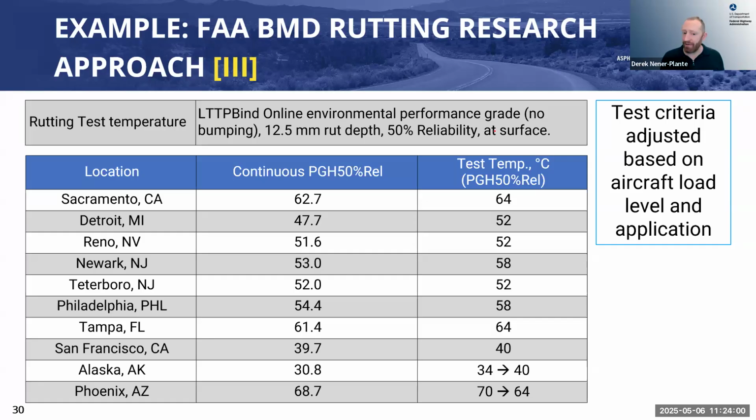I don't think it's necessarily significantly affected because the whole standard rests on the fact that you're going to do mechanical balanced mixed design testing at conditions that are indicative of your situation. And those conditions include aging and test temperature, right? And those are the 2 big variables that we see people adjusting.